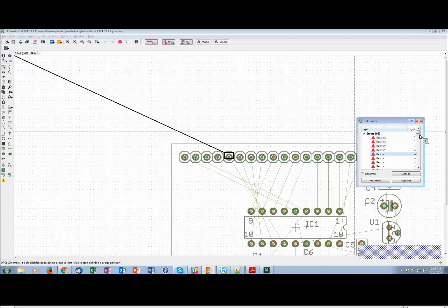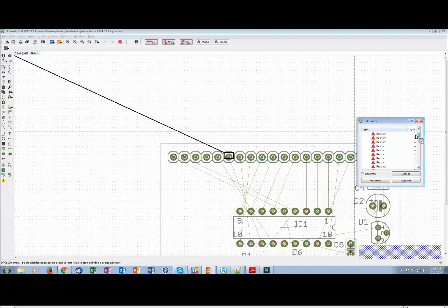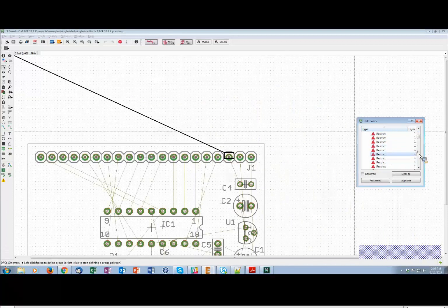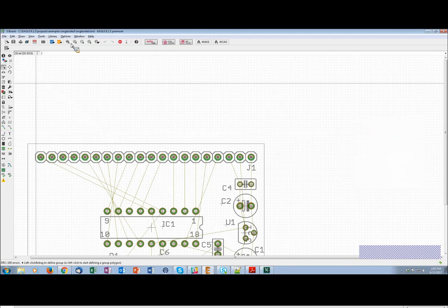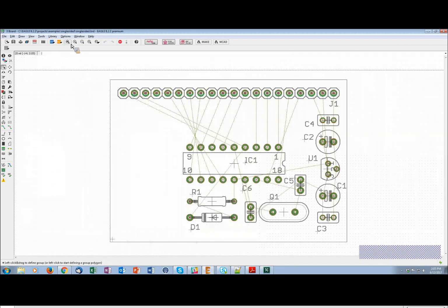What this represents is that the restrict layers control the Autorouter's behavior. So if we have, for example, a top restrict, the Autorouter will completely avoid it. In this case, it's not visible. I have that layer turned off, but it's always in play, as you can see by the DRC. So if ever you're running the Autorouter and you notice that things don't seem to be working the way you expect them to, this could very well be the cause.